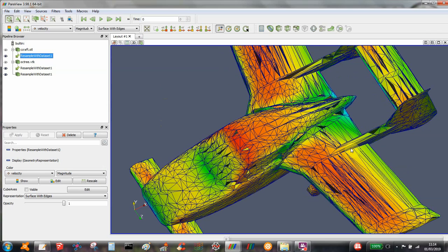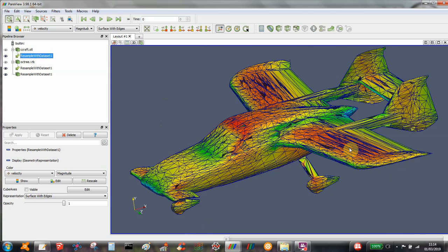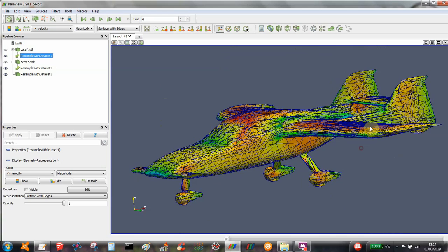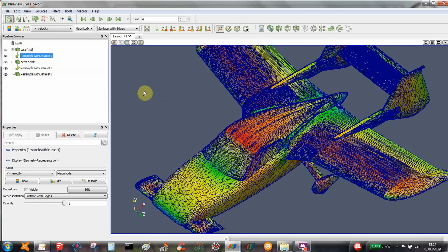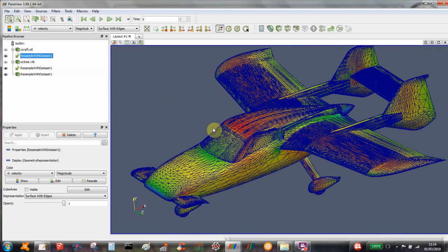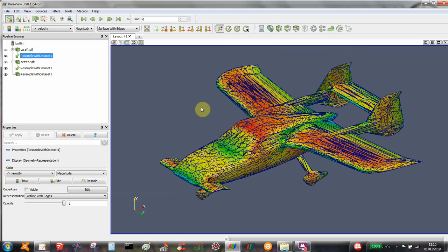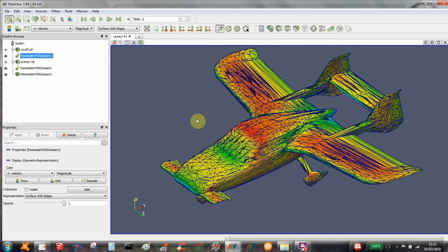But yeah, where you've got long triangles, like you have on the wings there, the flow solution is extrapolating onto very long triangles, so it's not going to be very good. So you want a nice uniform STL file if you want to use that resample with dataset feature.